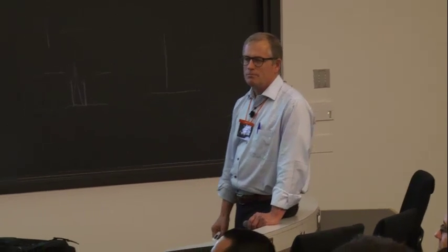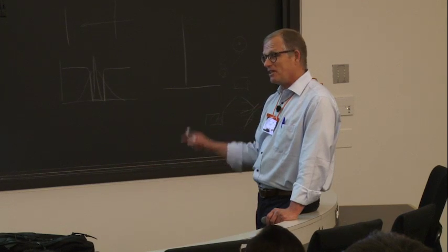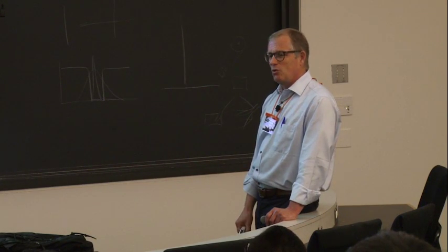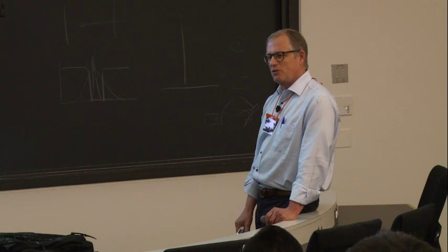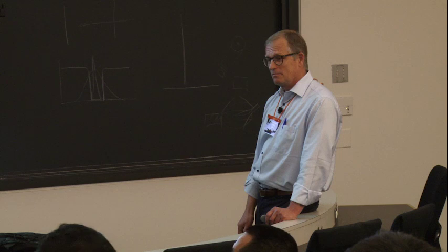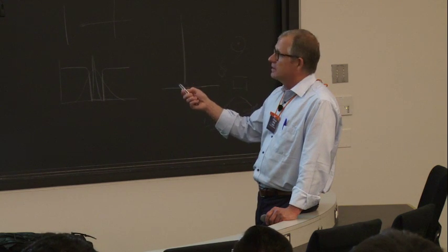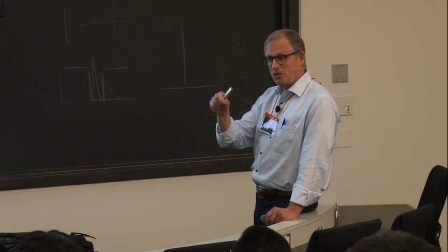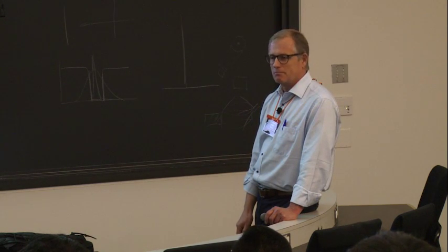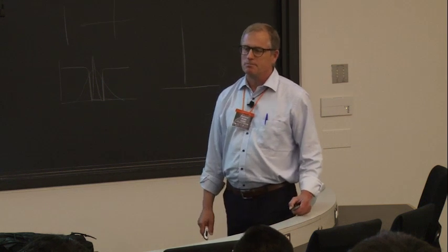What would you do to measure the velocity at this region? This is actually very hard to do. That's extremely hard to do. So what velocity do you actually want? Do you want the droplet velocity? Okay, you can just do phase Doppler anemometry right there, and at a single point you can get good quality droplet velocities. And you get size distribution at the same time.